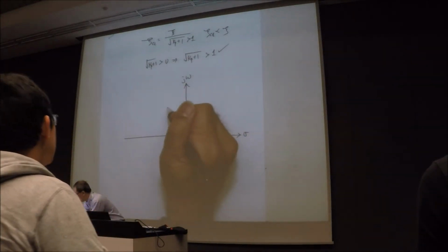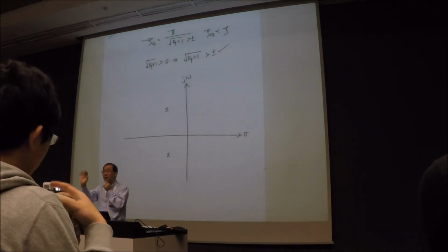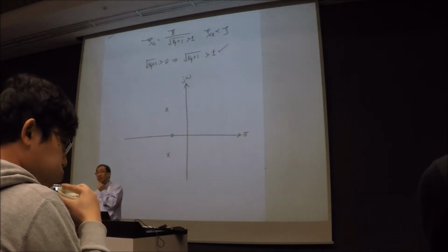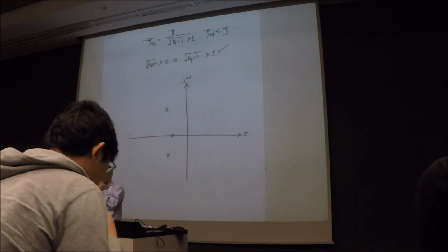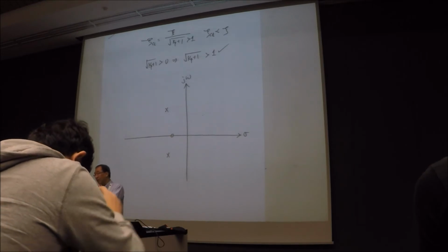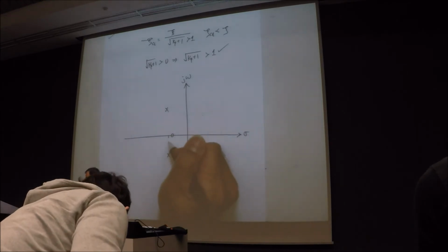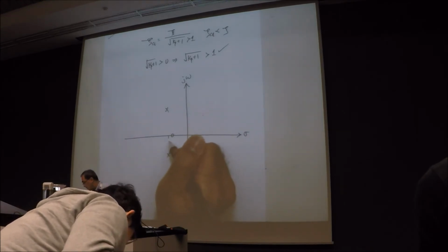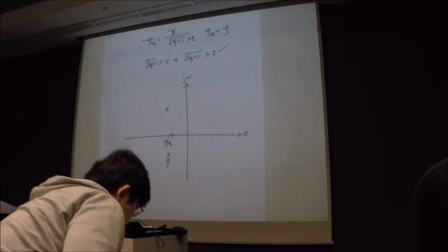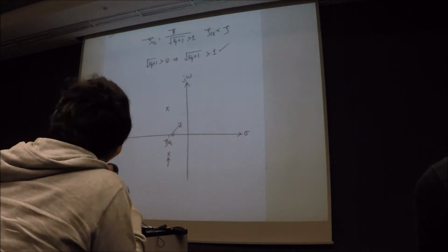Okay, so this is my closed loop pole location. As we mentioned, when you put an open loop 0, the 0 will stay put. So if I put a 0 somewhere around here, I'm basically saying that this 0 is close to the closed loop pole. I'm measuring based on the relative real part of your complex conjugate pole, the zeta omega n of this pair. So I'm looking at the 0 location and also at your zeta omega n.